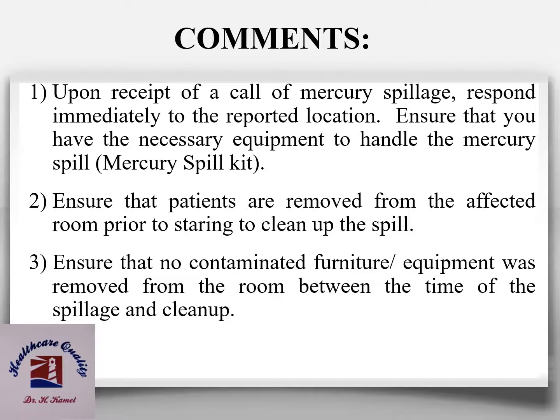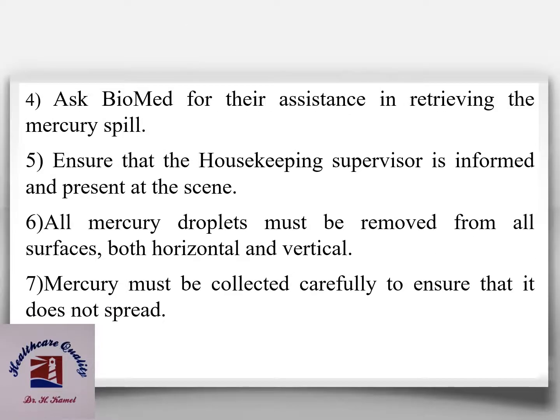Ensure that no contaminated furniture or equipment was removed from the room between the time of the spillage and cleanup. Ask Biomed for their assistance in retrieving the mercury spill. Ensure that the housekeeping supervisor is informed and present at the scene.